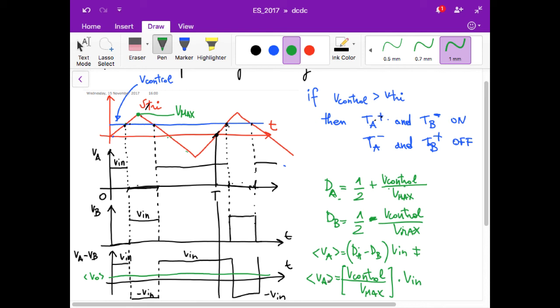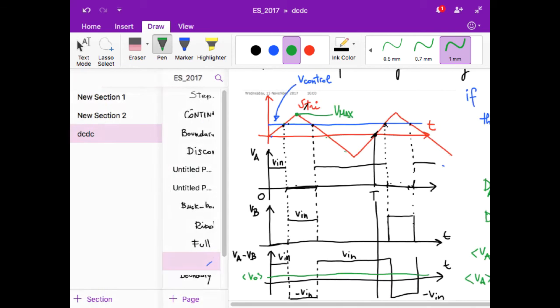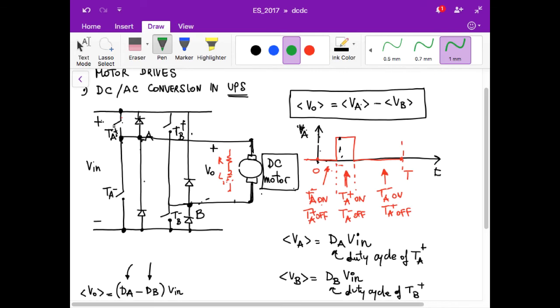So all this part is done in practice in a microcontroller, and then what is important is that those conditions control some output pins which are connected to the gates of 4 different NMOS transistors that can be opened and closed. So all the logic is done in a microcontroller. The microcontroller must have 4 output pins, analog output pins. Each of those goes to the gate of 1 different transistor, which acts as our switch.